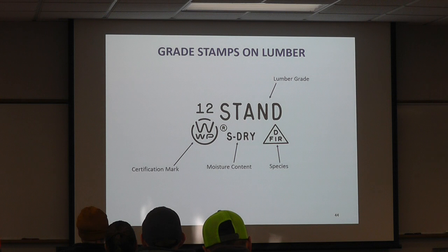So there's certification marks. There's the moisture content, the species of wood, and especially if there's a requirement to be a more dense wood, an oak or something, and they come out with a soft pine, you know, it's not going to fly. So make sure we understand what